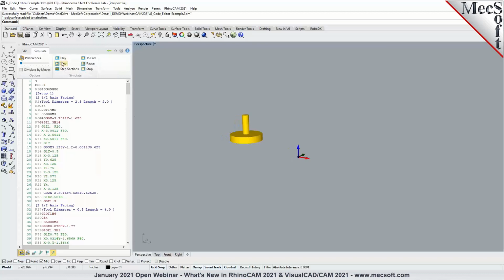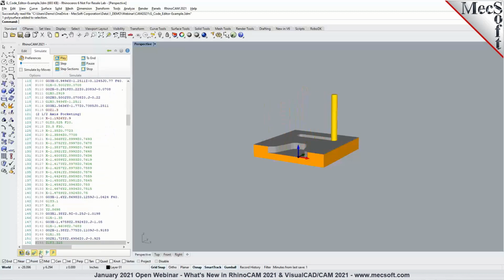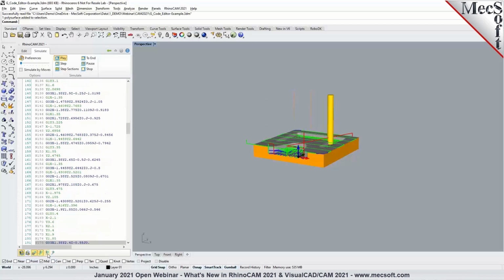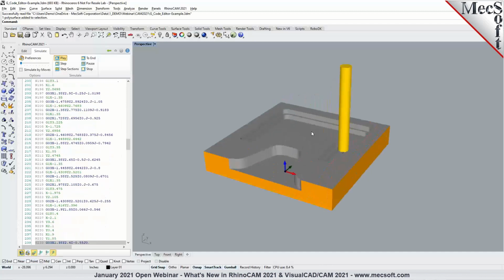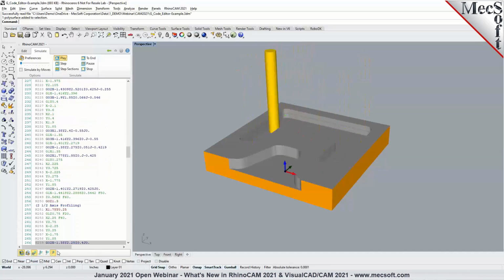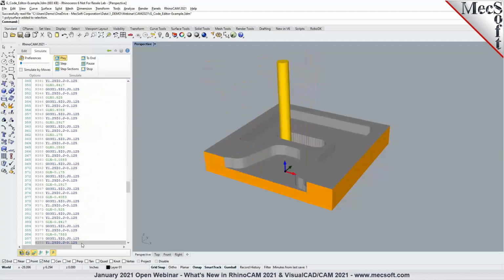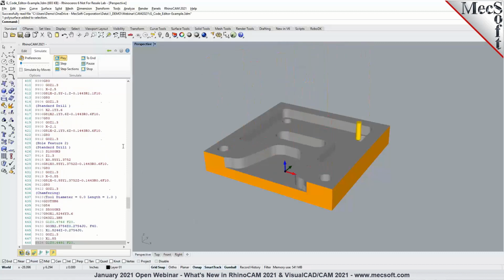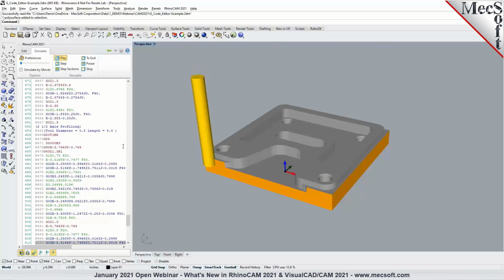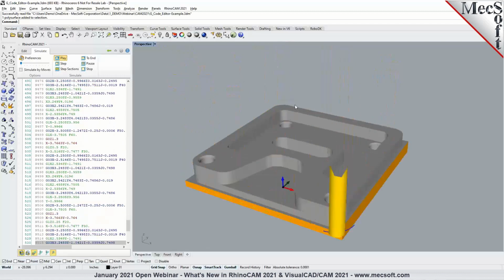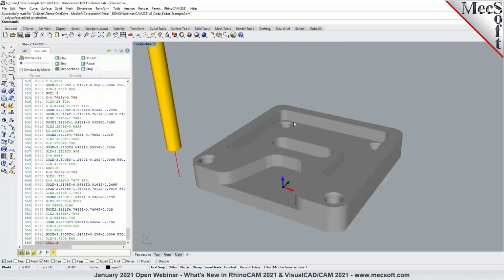So as you go to the simulate tab and then hit play to run a simulation, you now have the option to hide or show the toolpath as you're simulating. And you also have the option to enable the follow mode segment toolpath display as well. So these display toolpath toggles are available in the G-code editor module as well. You can hide the part and the stock visibility. You can toggle them as you're simulating or editing the toolpaths in the G-code editor module. So it makes it easier for you to view and analyze your cut material simulation of the posted G-code.